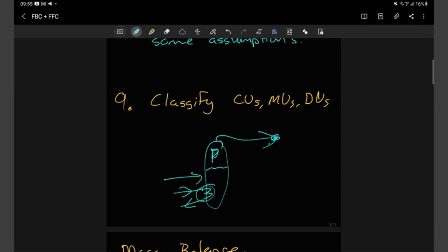So just note that disturbances aren't fixed to inputs. It can be something that comes from a downstream system, and the same goes for manipulated variables. It's not always inputs that you manipulate. Sometimes it can be an output that you manipulate to enable a form of control in your system. So be very wary of thinking that inputs are manipulated variables and inputs are disturbance variables. It's not necessarily the case, because these systems are connected in a lot of ways, or some of them at least.